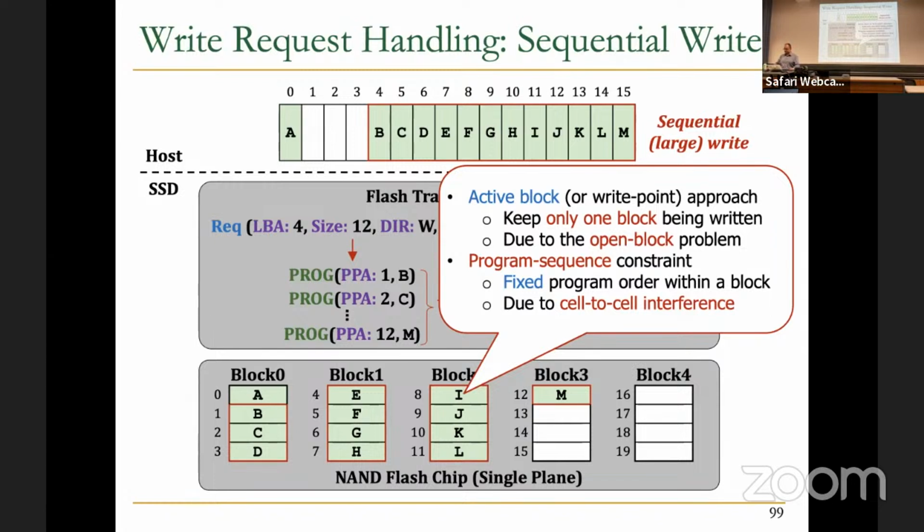My question was: why do we need to write dummy data to different pages to close an active block? Why not just keep them empty and move on to the newer blocks? There are some disturbances that are caused when the block is active and still has some word lines empty. These are not characterized yet in research works, but they are known in commercial SSDs. So that's the reason why we always program the blocks and close them. Thanks.